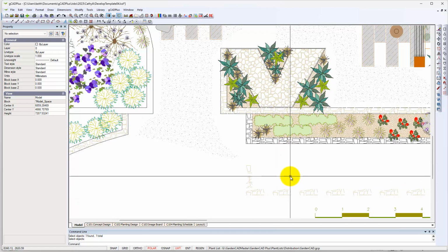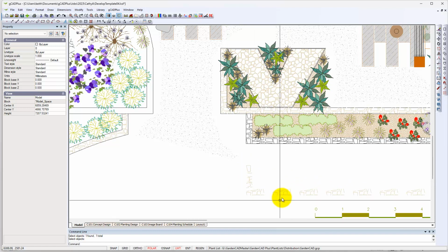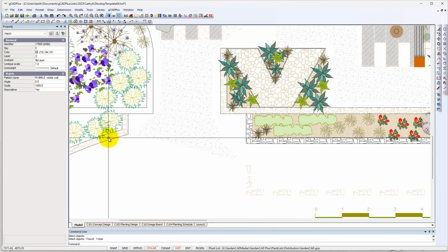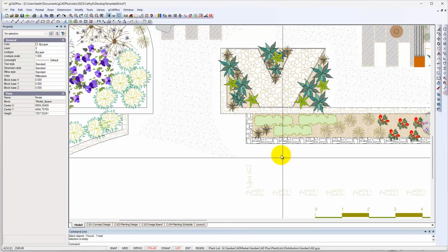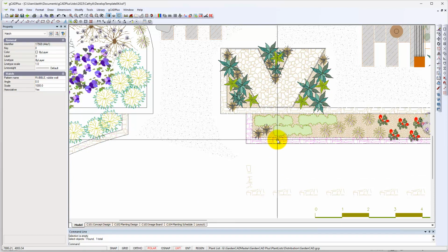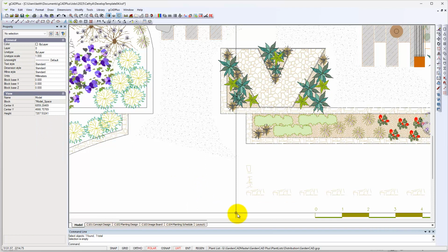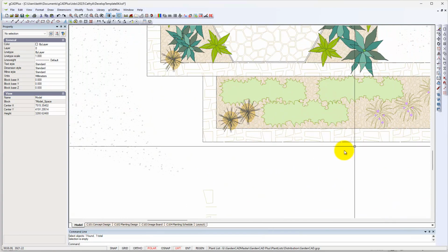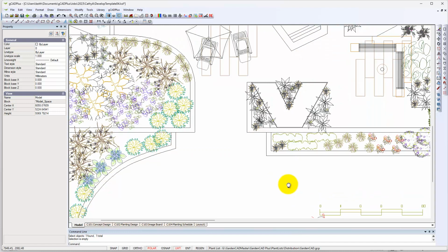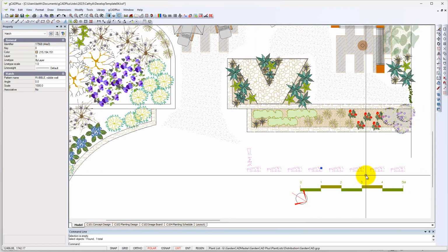And the reason what happened was that the match properties command failed to do, it did a job, but not quite as well as it should. So it's colour 215,194. So if we just change, don't use match properties, we just change the colour to 215,194, and we do that, and I hope you can see that looks fine. That's a proper hatch pattern. So I'll get rid of the one that was created using our match properties.